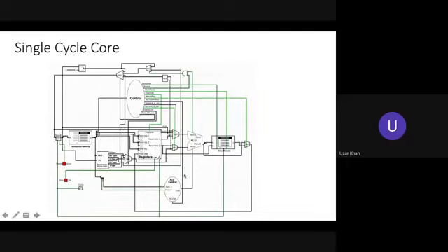Now moving towards the ALU, it basically performs different operations depending upon the instruction we have. If we have an add or subtract instruction from instruction memory, then it will compute the result, and the result will appear on the ALU result output. But if we have any branch instruction and the branch condition is true, then the ALU branch output would go high.